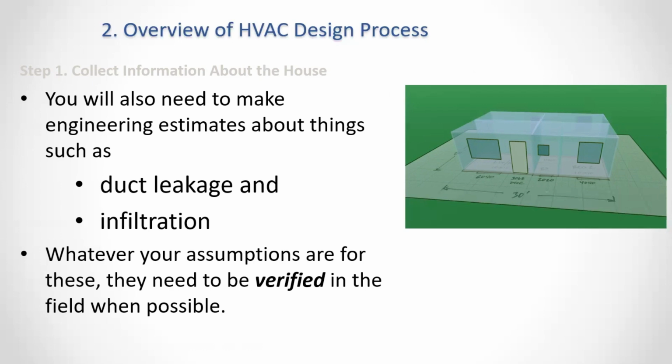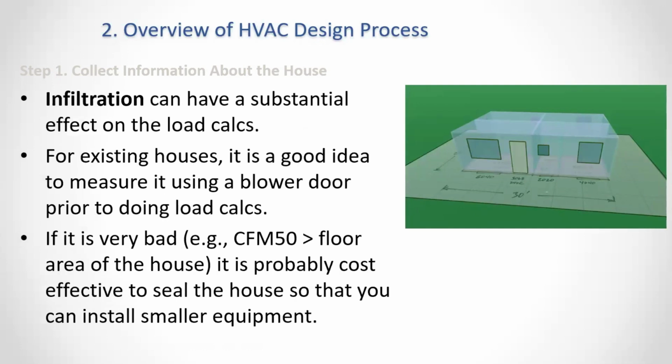Put some air in the tires, fix the car before putting a bigger engine in it. And that's just me, but the energy code will start paying attention to this. They will require that you don't assume a really leaky house when you do a load calculation. And I think that makes perfect sense. Next slide, please. So infiltration can have a substantial effect on the load calcs.